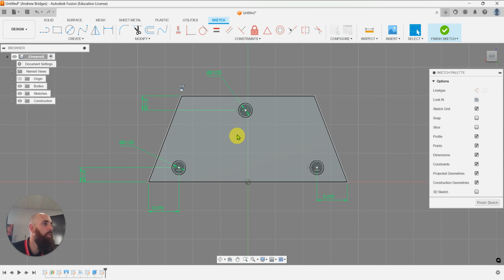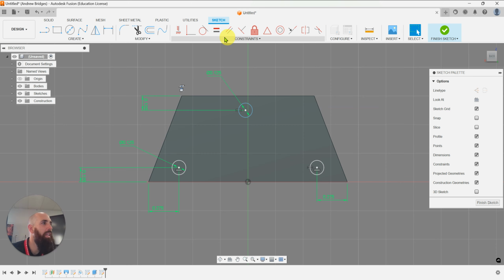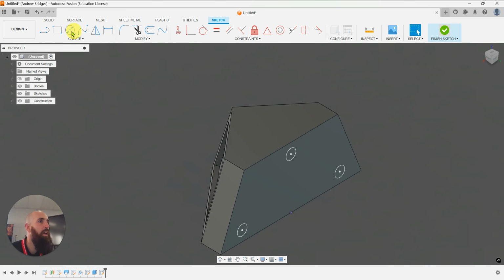And instead of a horizontal dimension, which we do see on our paper, we can tell that it's vertical with the origin point. So we can just snap it like that. And there we go. 3 completely white circles. Everything's fully dimensioned, ready to finish the sketch.